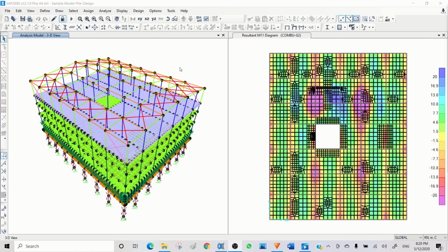Okay, so this is what I want to show you for preparing the model and completing the analysis and ensuring the basic results about deflections, about lateral stability, and about soil bearing capacity are correct. So we don't need to resize any element from a serviceability point of view or for the soil bearing limitations. And now is the time that we can say sections are correct and the model is ready for design.